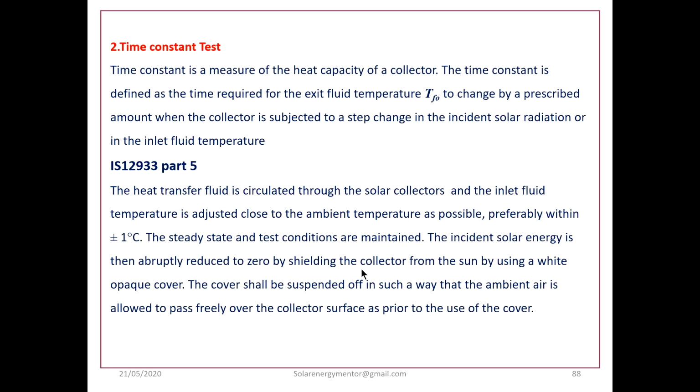Another test, besides the thermal performance test, is the most important test prescribed by the Indian standard. The second test recommended by the Indian standard is the time constant test. Time constant is a measure of the heat capacity of the collector, that is, how a collector responds to a change in the input and output conditions.